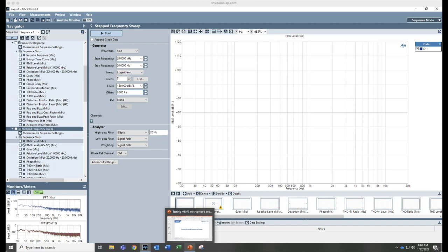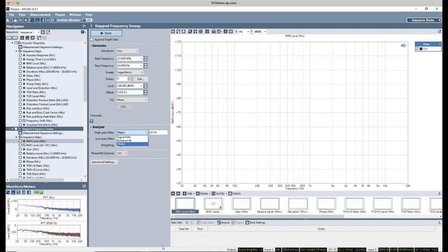So if I'm making voice application measurements where my frequency range of interest is a few hundred hertz to 10 kilohertz, and I'm doing it free field, both microphones work just fine. But the pressure field microphone's phase response is flatter. And this is, again, quarter versus quarter, free field to pressure field. A pressure field microphone has a somewhat flatter phase response. I somewhat brushed by it, but just to bring that up.